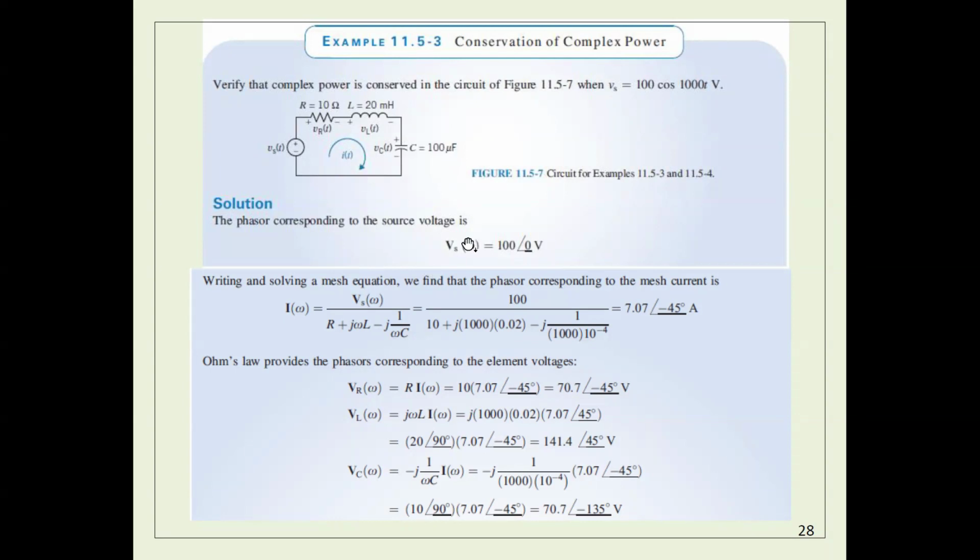Here I give you V. V is given to me. Okay? So you can calculate the total impedance here, which is actually R plus J omega L plus 1 over J omega C, or minus J over omega C. Okay. So now I have the voltage. I can calculate the total power this way, and by this way I can calculate the current. This current is in series. Okay.